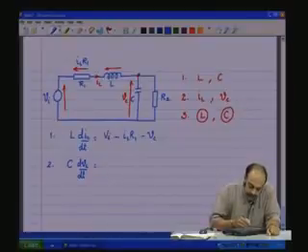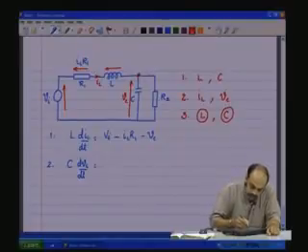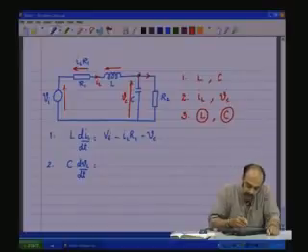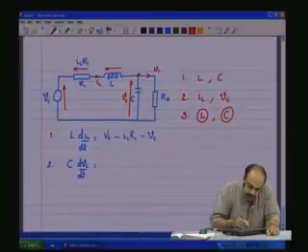So here we have IL, and what is this current here? The one which flows through R2. Can it be expressed in terms of state variable? We know that the node voltage here is Vc. So Vc by R2 is the current which is flowing through R2 here.